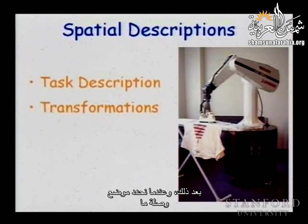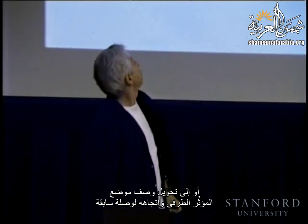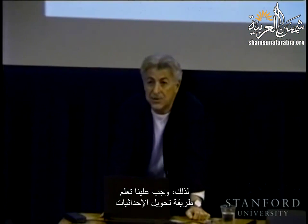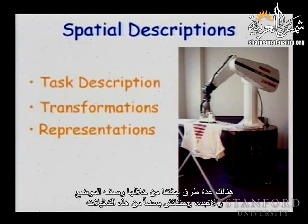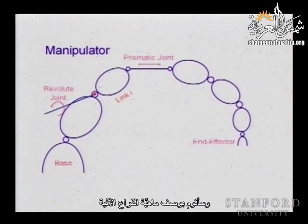Then, obviously, when we determine the location of a link, we need to be able to transform that description to the next link or to describe the position and orientation of the end effector in a previous link. So we need really to handle transformations. Then we need to discuss how we represent the position and orientation. There are many different ways through which we can describe a position or an orientation, and we will discuss a few different representations. And I'm going also to describe a little bit what is a manipulator, what is a robot arm,